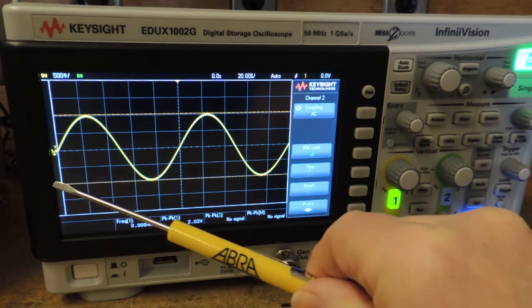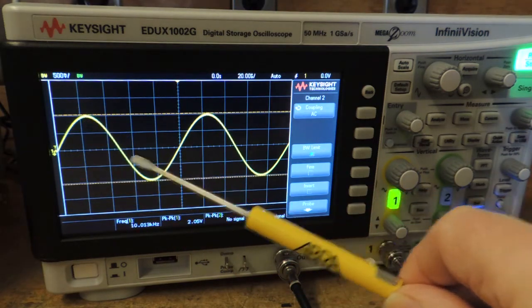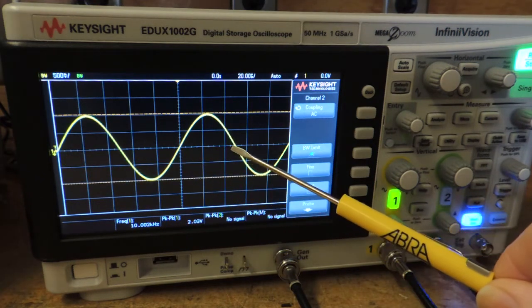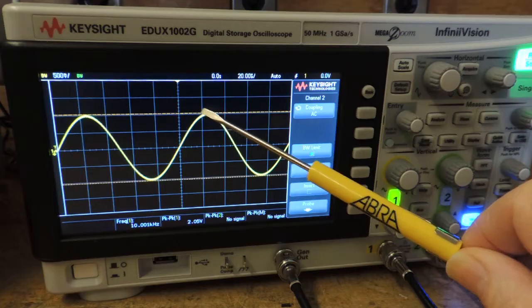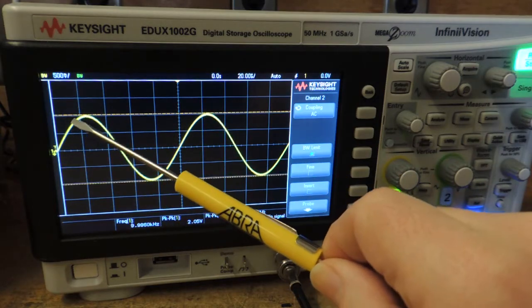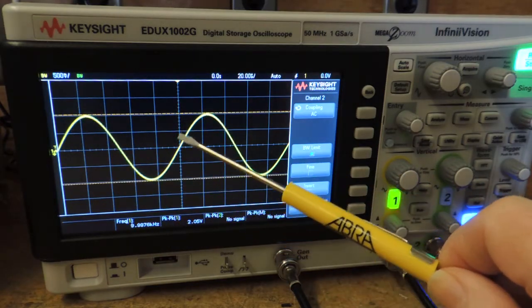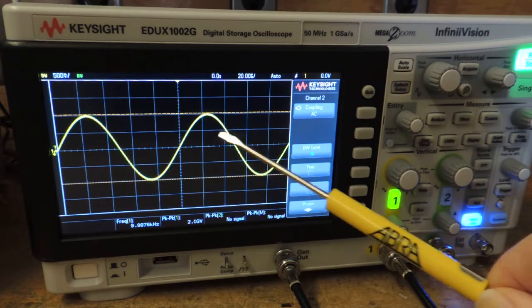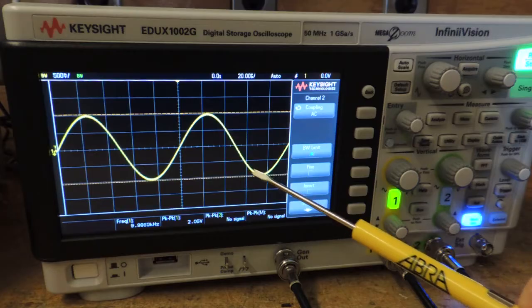So now I can sketch this waveform fairly easily. I can find out where the 0 points are on my plot, and then I can find the peak, and then I try and draw my waveform as best fit as possible. Remember, it's not a triangle wave, so try and get some curve at the top and the bottom.